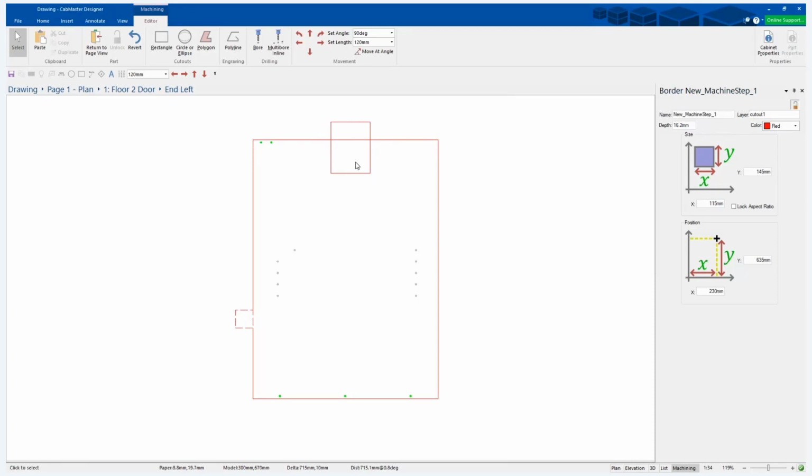When you send it to the machine, this first one here with border plus will actually do that as one piece. This one here will actually do the border, then it'll come back and do a second cut there, and it'll cut this entire shape. So it'll cut into the part next to it. This is where it's important to know what the layers are doing.